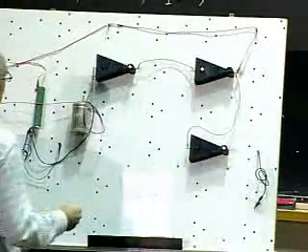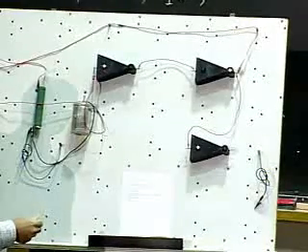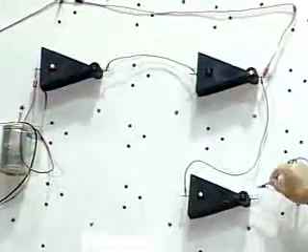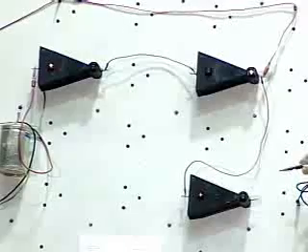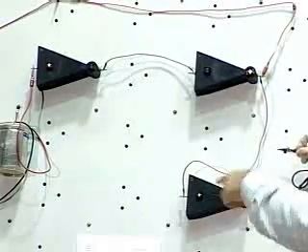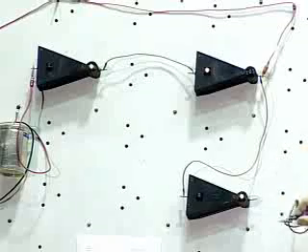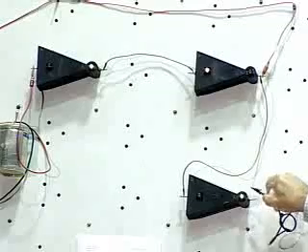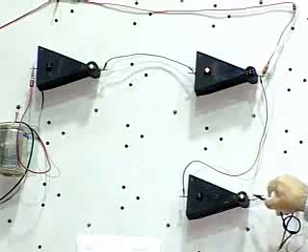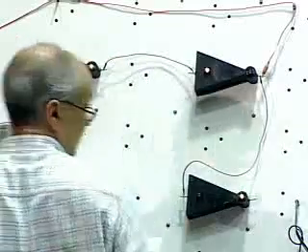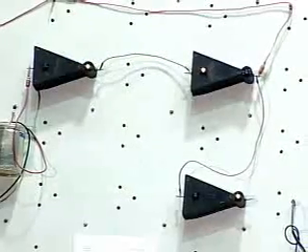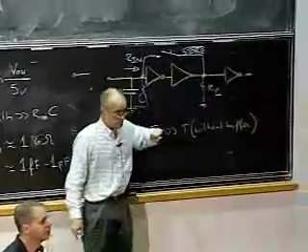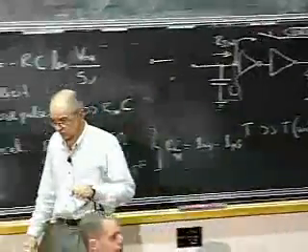Okay, now of course we disturb the input. Okay, now of course I can do anything I want here. Nothing happens, but you may say this is a trivial case because this is already 0. So I'm going to change the state. Here's the change state changed. Now, see, I can short this. Nothing happens up there. So this is an interesting situation in which I'm buffering the output so that the output does not feed back to the input. And by and large, in designing circuits, this is something that we do.